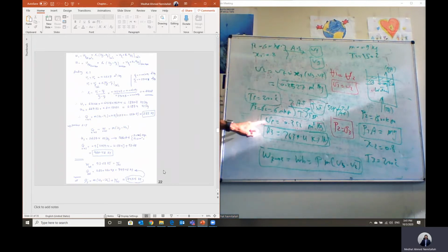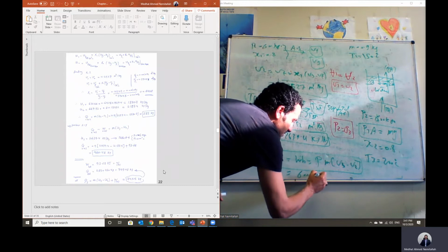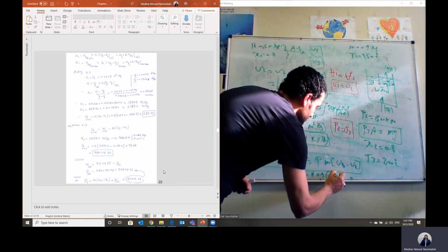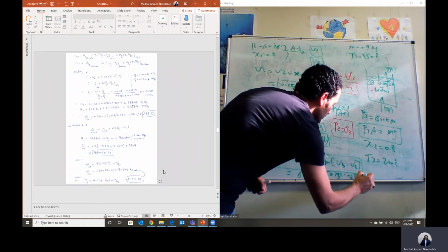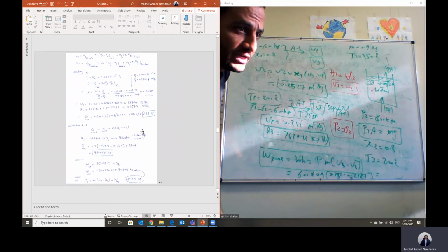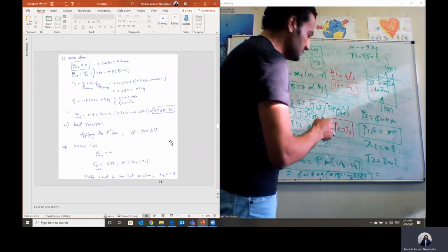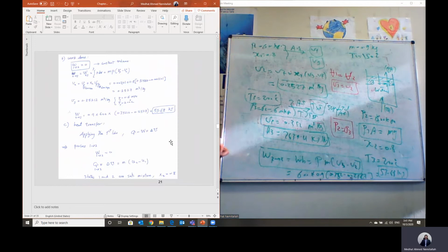Okay. Then come here. We have the specific volume V3 and the specific volume V2. We have the pressure, which from 2 to 3 is fixed at 600 kilopascal, multiplied by the mass, which is 0.9, multiplied by V3, 0.352, minus specific volume V2, 0.2527. Then we can calculate the boundary work from state 2 to state 3. It equals 53.68 kilojoule. And this is the work from state 2 to state 3.